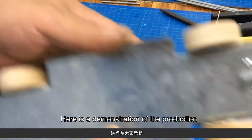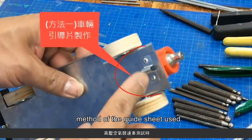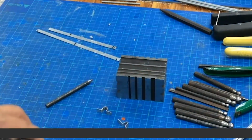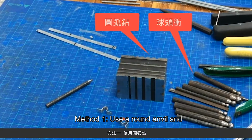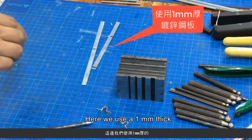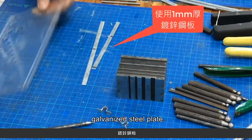Here is a demonstration of the production method of the guide sheet used in the test of the compressed air racing car. Method 1. Use a round anvil and a spherical punch to make the guide sheet. Here we use a 1mm thick galvanized steel plate.